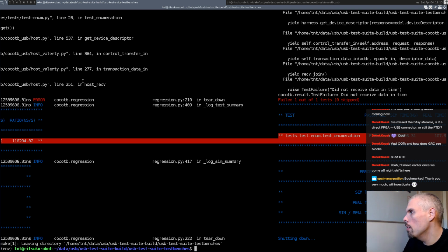In my last stream, I talked about I/O timing and stuff like that, and the SPI one is because I was actually working on a SPI core for the BitC, which is going to run in quad SPI mode at 96 megahertz, which should provide me with like 48 megabytes per second of bandwidth. That's the same reason I also developed the memory cache, which I presented on a previous stream as well.